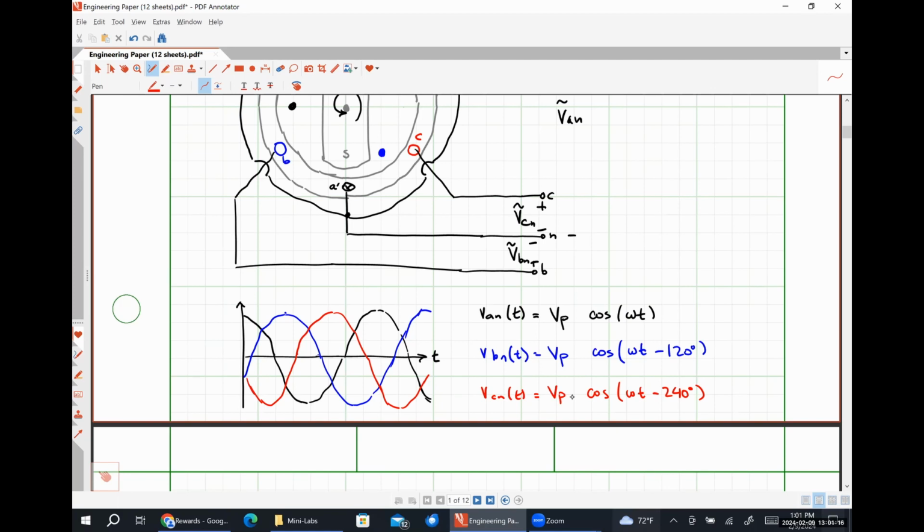So let's say that we used 18 gauge wire to connect the A phase of the source to the A phase of the load and 8 gauge wire to connect the B phase of the source to the B phase of the load. Because those wires have different cross-sectional areas, they are going to have different resistances, and therefore there is going to be some imbalance in the system. On the load side of things, we could just effectively have something plugged in between A and neutral and something not plugged in between B and neutral to generate an imbalance.